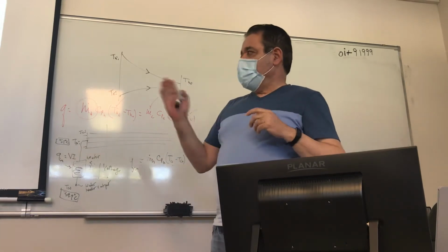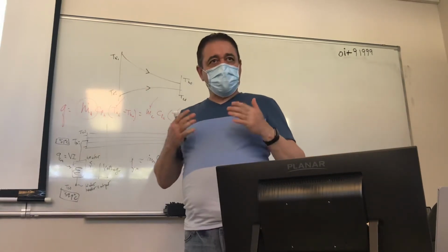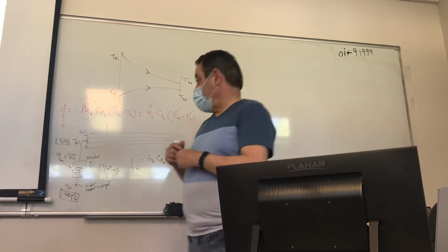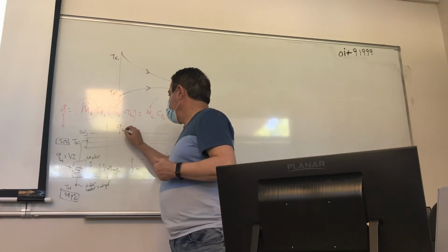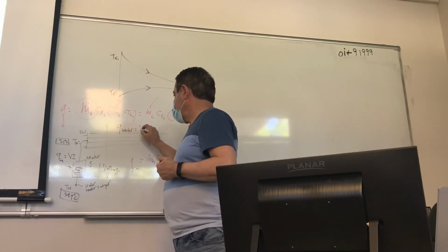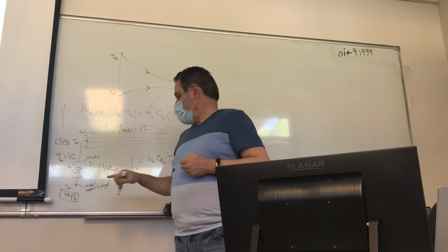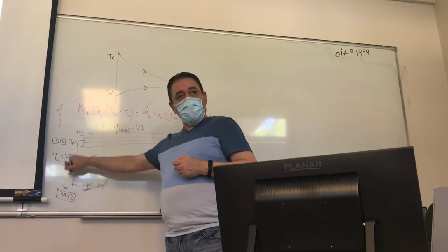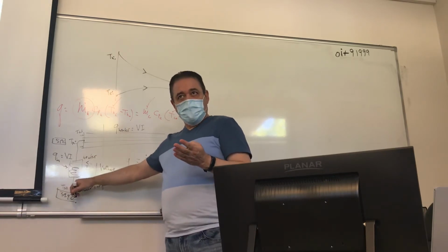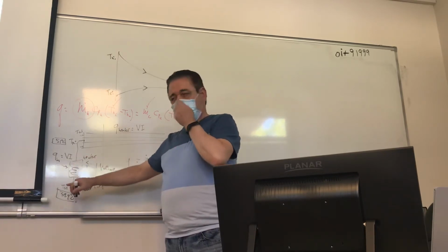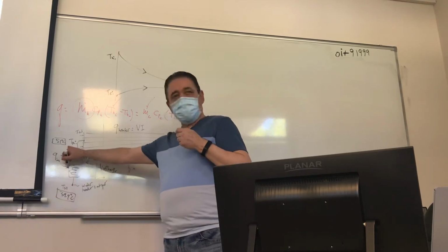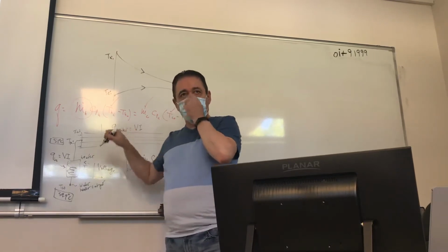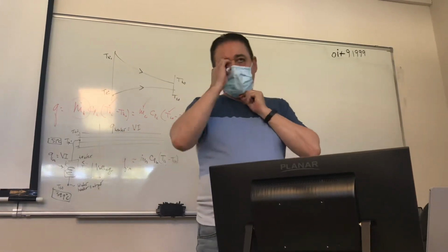Then from there you can figure out what is the efficiency of the heater. In other words, out of that heat generated by the heater, which is Q heater, essentially equal to just VI, once you calculate the energy used up by the water, how much energy it took to raise the temperature of the water from 39.9 to 51, that should tell you what fraction of this it has used, and from there you can get the efficiency of the heater.